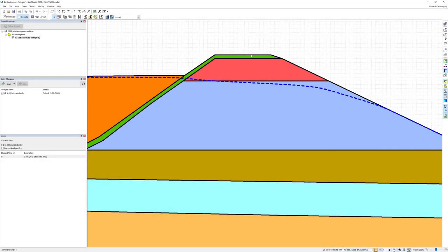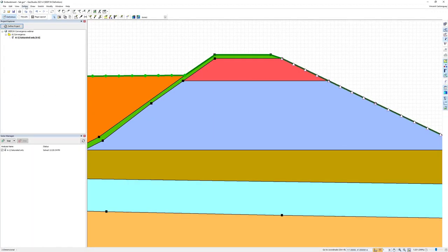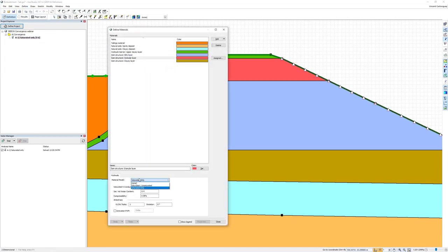Now that we have identified zones and materials where unsaturated flow occurs in step 1, we should switch the appropriate material models from saturated only to saturated unsaturated in SeepW. As you can see, this material type requires 2 entries in the form of functions, a volumetric water content function and a hydraulic conductivity function. These functions should ideally be measured in a laboratory for better results, but can also be estimated within SeepW. Let us review what both functions refer to.